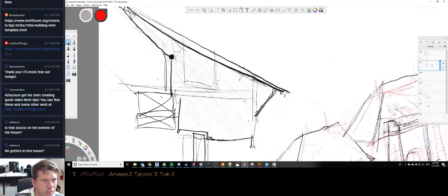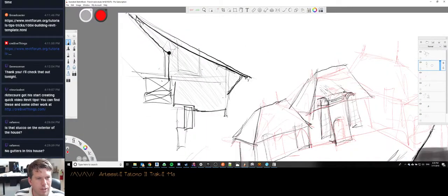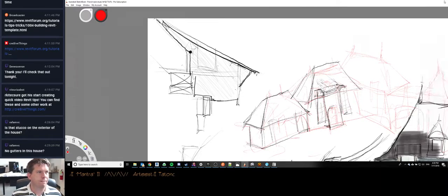So here's a little sketch right here. You've got the wall plate right here, a rafter sitting on top of it, with the curved framing sitting right here, and the gutter will be internal right there, and then it'll come down through the soffit with a copper or brass leader.